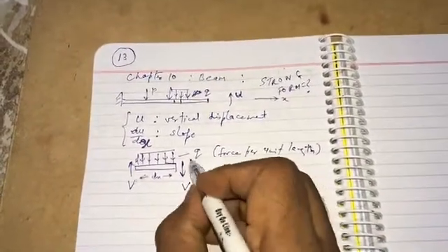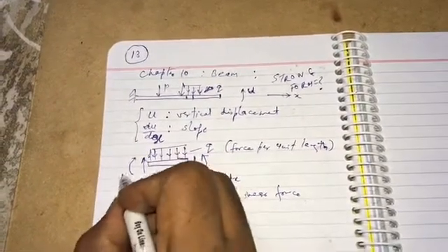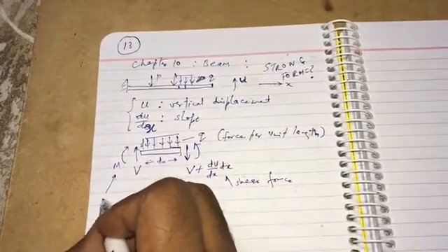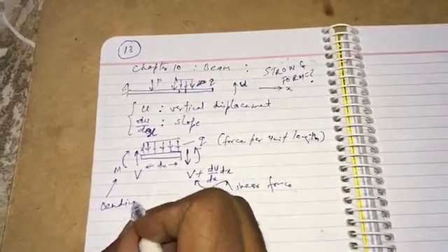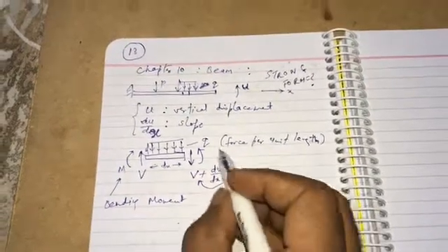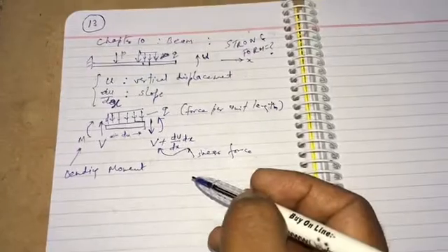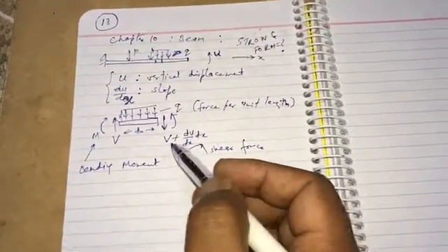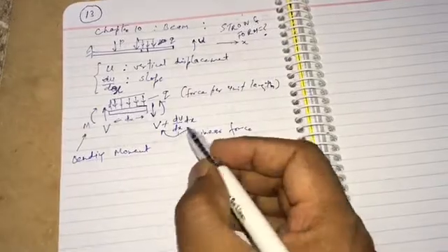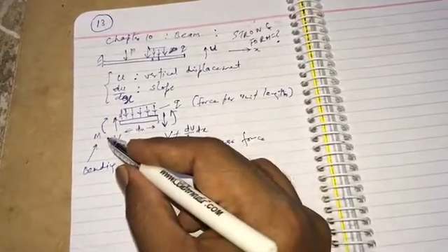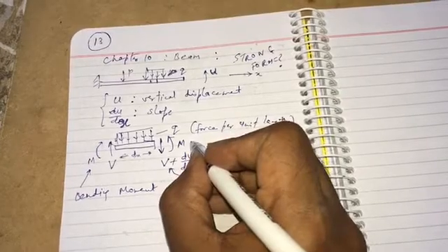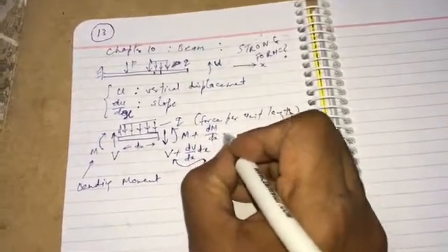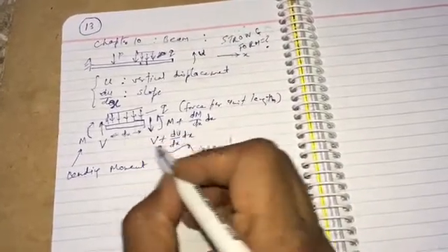There is another type of force here, which in this case is the bending moment. So M is the bending moment. All those things you must have done already in a solid mechanics or strength of materials class in your second year. Here I am just going to repeat them so that you remember and can solve the problem. If it is M here, because of the variation M will change to M plus dM over dx times dx. This is how the variation is.